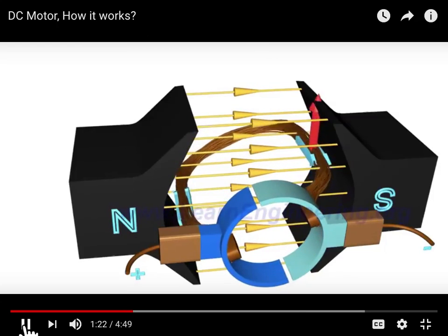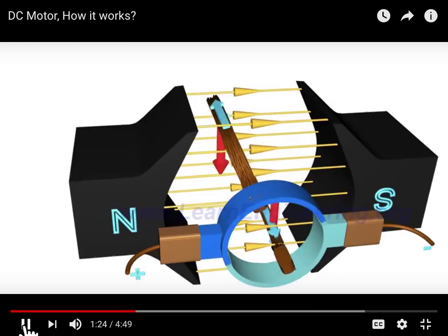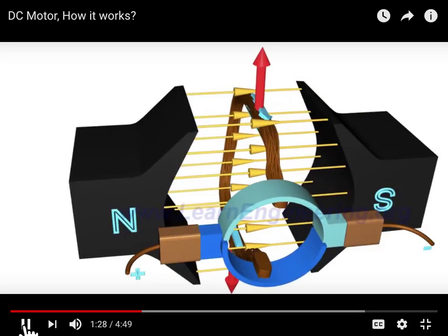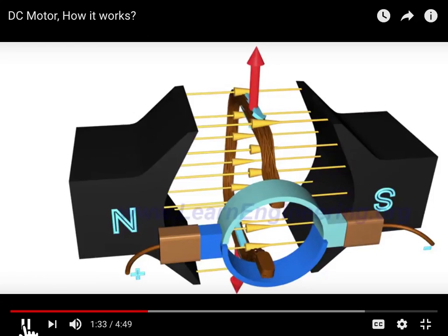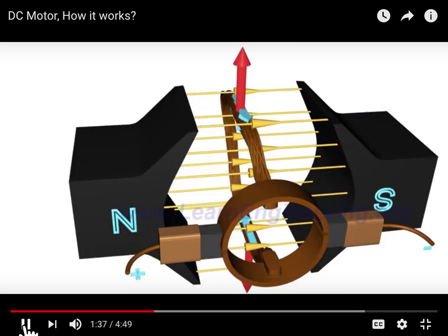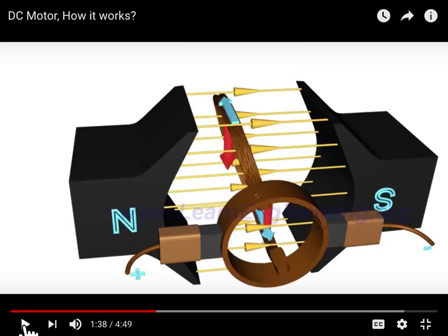If you observe the torque action on the coil closely, you will notice that when the coil is nearly perpendicular to the magnetic flux, the torque action nears zero. As a result, there will be irregular motion of the rotor if you run such a DC motor. So this kind of DC motor isn't great because when you get to that perpendicular position, it does have to kind of run on its own momentum. You have to turn it off and just let it go.